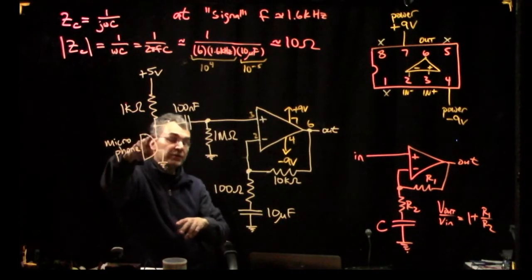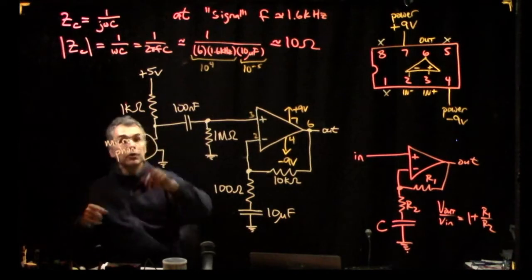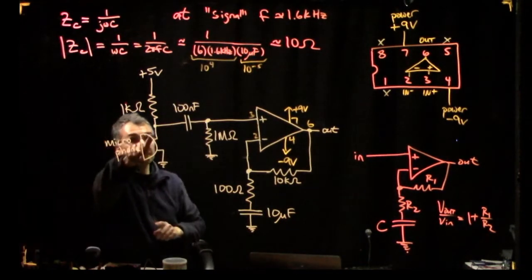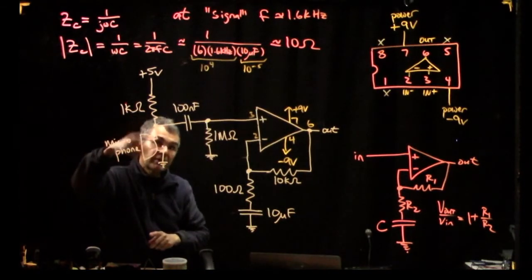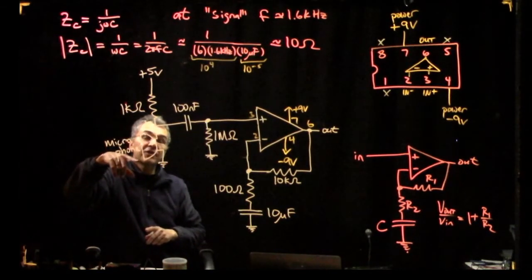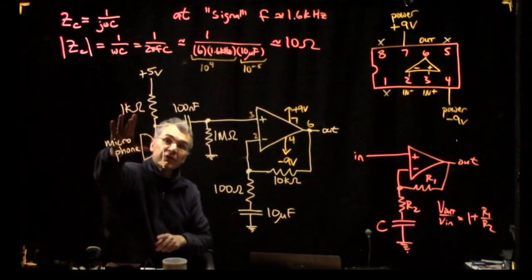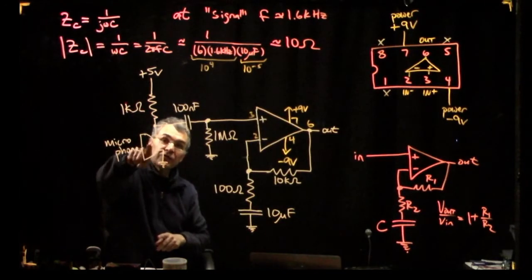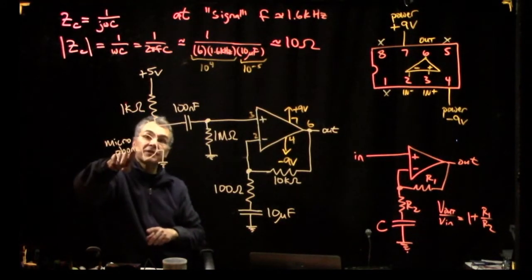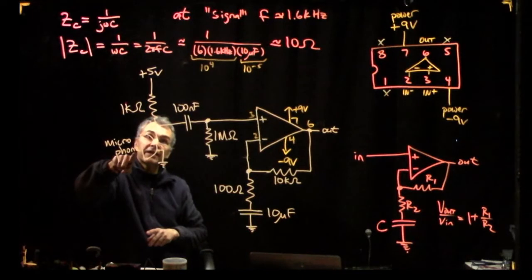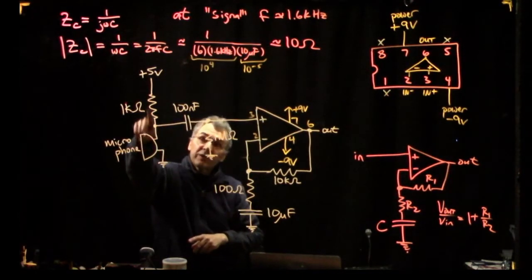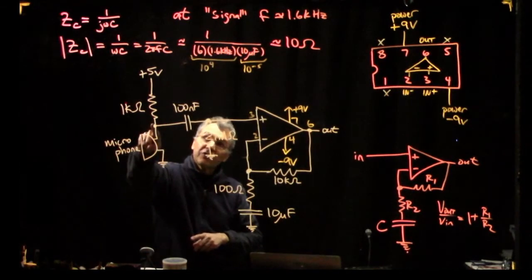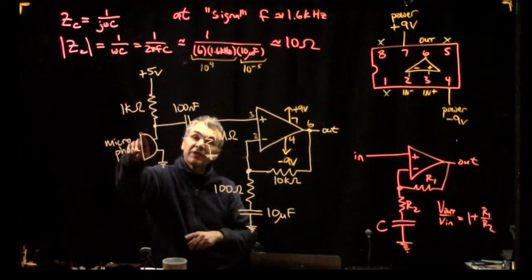So when we look later with the scope probe, we'll see that this point stays pretty close to 5 volts, just a little bit less, but it wiggles up and down. So then you do get a signal, okay? The fact that it sits near 5 volts is what it needs to be powered internally. And the fact that it wiggles around gives us a signal that we can look at and amplify.